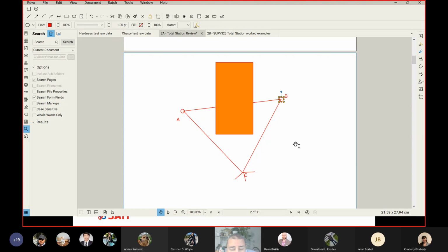And I'm very precise. I'm not saying to measure AB, I'm saying to calculate AB. A slope distance and a vertical angle, a slope distance and a vertical angle. Is that enough, or am I missing something? Go to your math class. You're missing the horizontal angle between the two of them. Thank you, sir. That's exactly what I'm pointing to.